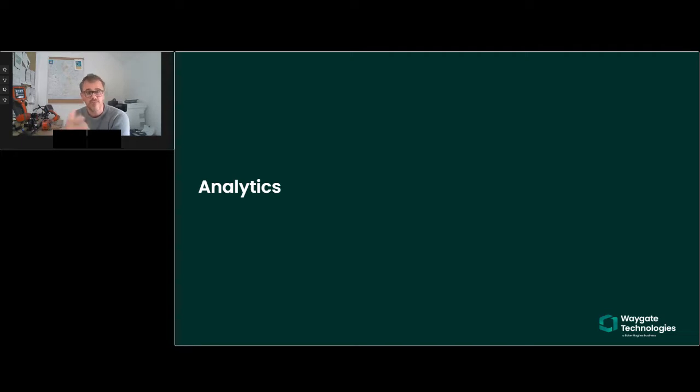As we move forward and develop and enhance this capability, we'll be working towards making that happen in a live sense. But at the moment, in the near term, we have still ADR analytics that are available to you on the borescope. And then by pressing the live analytics page, you get to see a blade counter, another example of helping you carry out your tasks such that you can spend most of your time doing what you're really meant to be doing, which is performing an inspection.